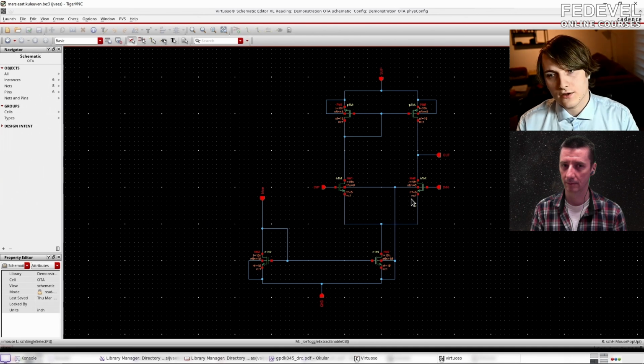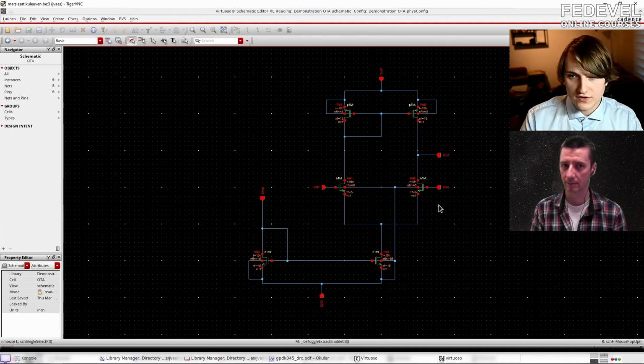And then from that, we can calculate the gain. And so to do that, to get a certain output resistance, you might make the transistor longer, because then, of course, it makes sense if you think about it. If you put more resistances in series, right, you get higher output resistance.